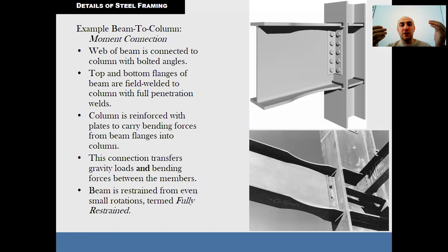Instead of bolted beam-to-column connections, welded connections can be used in these constructions, like portal frames. Welded beam-to-beam connections can be prepared in the fabrication shop with a bolted splice connection within the beam span or at a position of low bending moment.